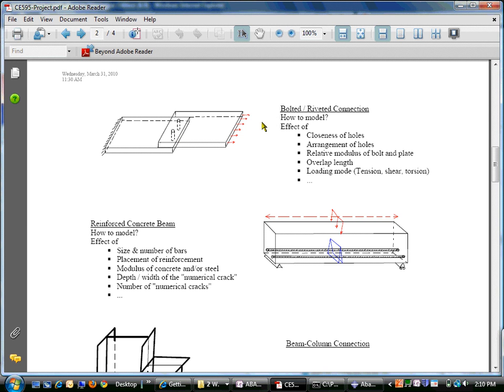Maybe a couple of hints here: try to generate a model that is monolithic, meaning if you generate one mesh for this entire big thing, it might have some interaction going on at this edge.